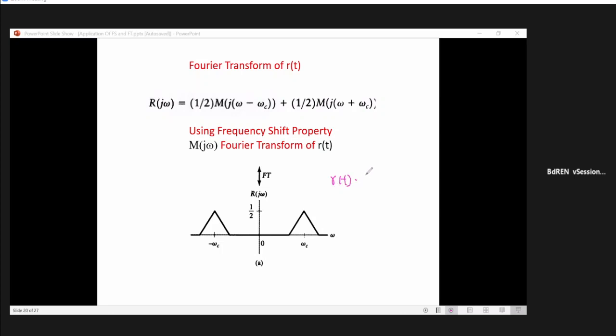Again, at the receiver, we are creating another carrier with the same frequency, isn't it? We are multiplying it in this way. You got the point? Yes, sir. And that multiplication, what will happen then? This multiplication in the frequency domain will be equal to 1 by 2π times the convolution.